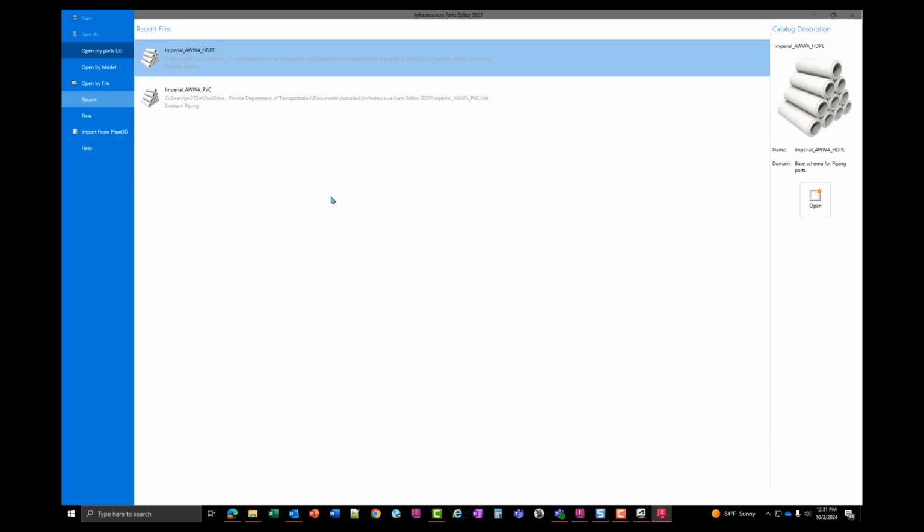So instead of Part Builder doing it all on one part, all the sizes, all the shapes, tops, bottoms, you have subparts that go in here, assemble them into one. And I'm not going to get into too much detail of that, I'll show that in the video. But after the part is assembled, then you export it out to use in Civil 3D or InfraWorks.